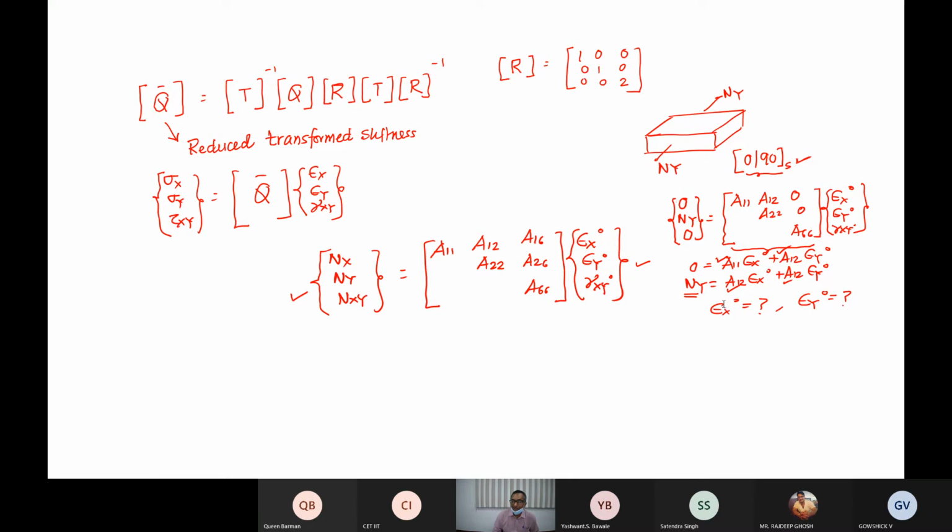But of course, we do not load a single lamina. We actually make it sufficiently thick following certain standards and then find out. I think I told that also. We take around maybe 6 to 8 0-degree plies to make it thick, and then it has a standard length following ASTM standards, and then we load it in a UTM to determine E1. Similarly, when we try to find out E2, we make sure that it is sufficiently thick.